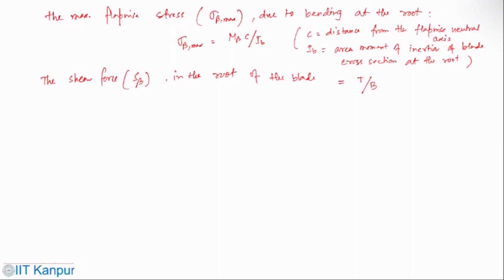If I have to summarize the flap forces and moment for an ideal rotor, bending forces and stresses vary with the square of the wind speed and are independent of blade angular motion or position, which is azimuthal. The blades on rotors designed for higher tip speed ratio operation have smaller chords and cross-sectional area moment of inertia.